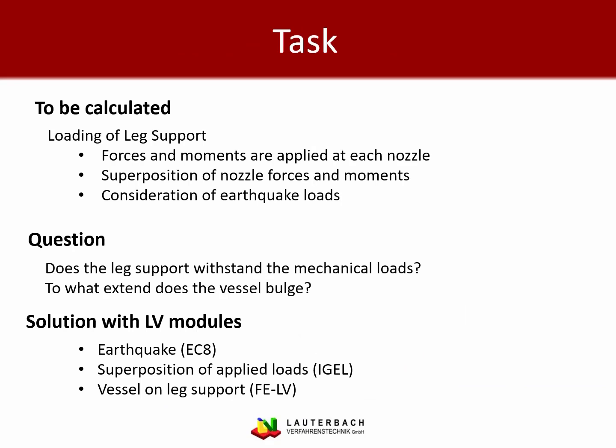We want to calculate the loading of the leg support. We know that at each nozzle there are forces and moments applied. We know that there is superposition of all those nozzle forces and moments, and we want to consider the earthquake loads. So the 2 questions that we want to answer are if the leg support withstands the mechanical loads and to what extent the vessel bulges.